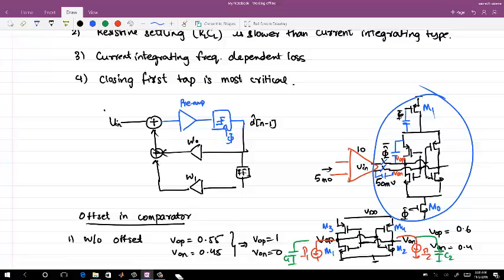The loop delay which we are still looking at is going through all this if we go through the regular procedure, and at the input of the comparator. Because what I am concerned about is what I am going to make a decision on. Yes, you can increase the preamplifier gain, but that is not reducing the delay. So you can say the concern has now changed from having some amount of gain to the delay becoming more of a concern.